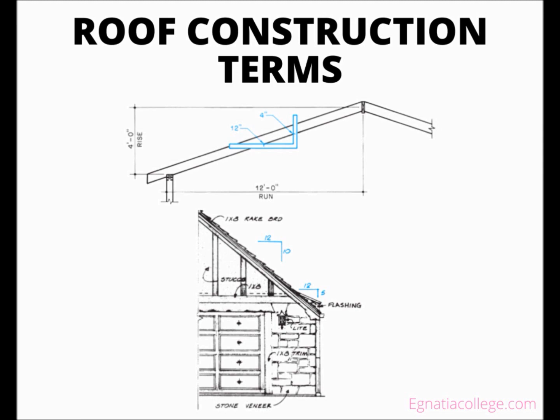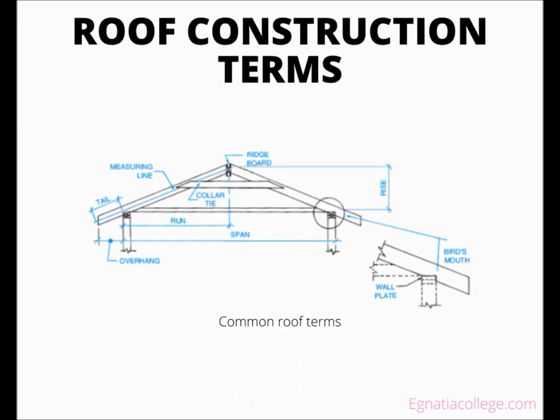By planning the slope and overhang of the roof, the designer can minimize the amount of scrap material that is generated in its construction. The ideal dimensions for a roof section would be in 2-foot increments. Most roof framing is spaced either 16 inches on center or 2 feet on center. A roof that is multiples of 2 feet in length and width, ridge to eave, will not require extra framing if it is framed 2 feet on centers.